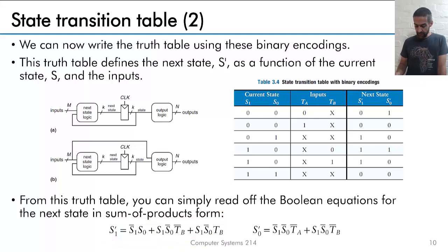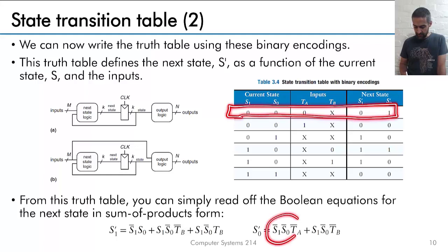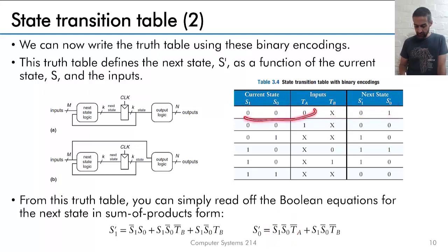All right, then moving on, this function here, the least significant bit of the next state logic, is this column here. And if you think about this one and that one there, this is simply equal to the AND of the two inverses. And this one, it's actually that term there. All of them are 0.